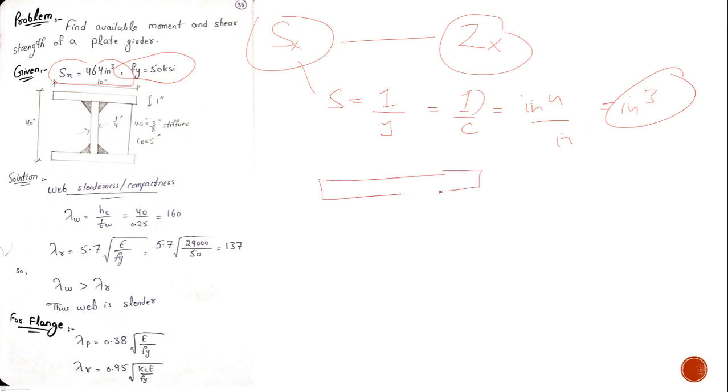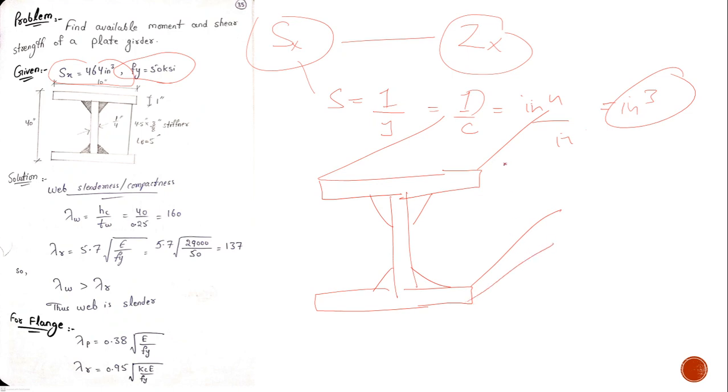So this is your plate girder. It has a very long flange and a deep web or deep stem, and you have fillet welds, and we studied welds in the previous lectures, in our very first lectures. Some lateral buckling requirements are also given, like the stiffener used is 4.5 inches by 3/8 inches. It means this length is 4.5 inches, and if you look from here, you will see a stiffener like this. Its thickness is 3/8 inches.